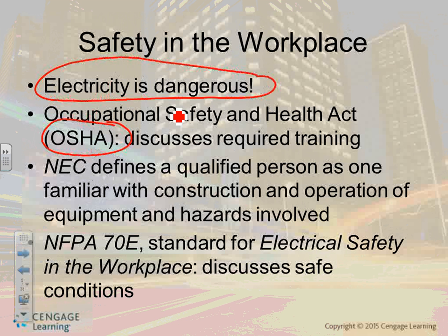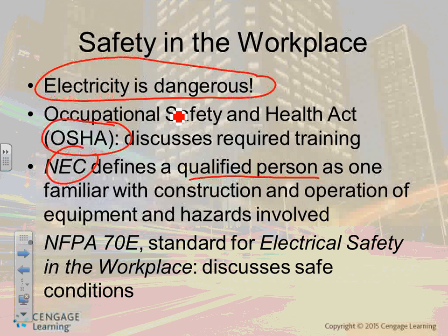We talked about it in the secret book, guys. I defined a qualified person. You guys remember that one? Somebody like you who has skills and knowledge, that's you, and has received safety training. Skills and knowledge in the related topic. So if you're doing lighting, you have to have skills and knowledge in lighting. If you're doing power, you have to have skills and knowledge in power. And have received training to recognize and avoid the hazard. So what's the hazard in changing the ballast? Recognize the hots, which one is hot, which one is not hot. And what happens if you short that panel?